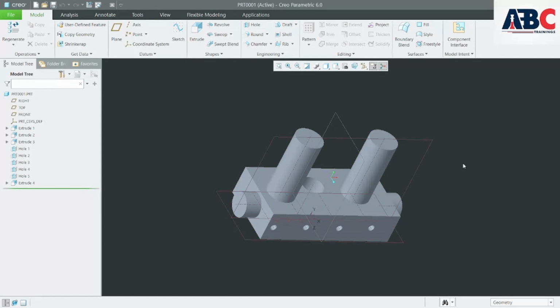This box doesn't affect the part itself, but it helps in organizing and checking for any interference with other parts in your design. It's especially useful when working with large assemblies because it shows you the area or space a part needs without being a part of the actual design. For example, if you're designing a robot and want to know how much space a motor will take up, you could use an envelope to outline the motor size. This way you can avoid collisions with other parts. In short, an envelope helps keep your design organized and ensures that different parts fit together without any conflicts. Okay.